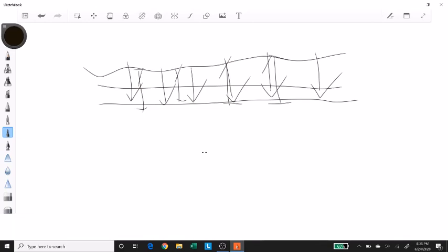Usually we use a reference point whose elevation we set. So let's say I am doing survey over here. I can select one point, which is usually the lowest one, and I can give it an elevation of 0.